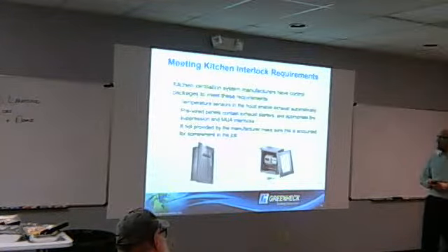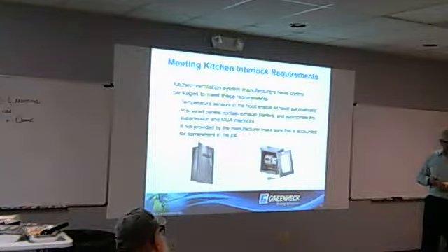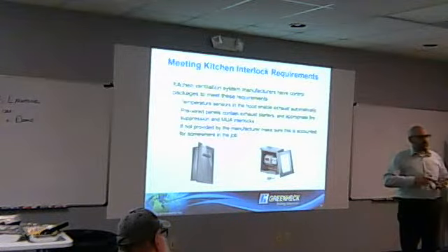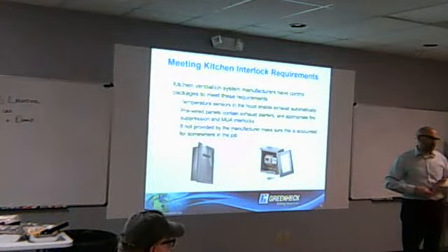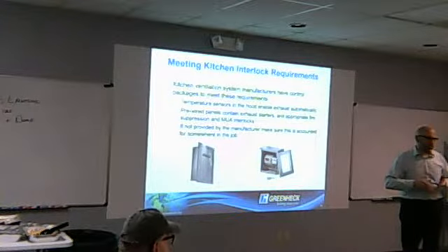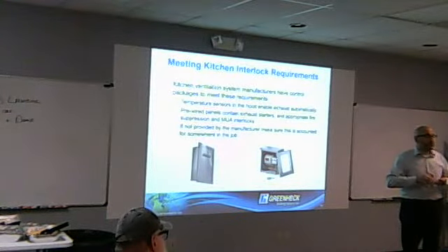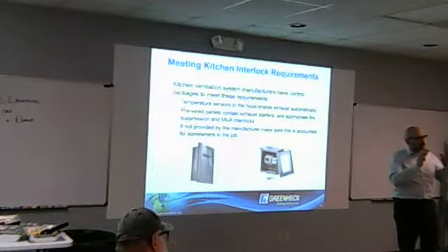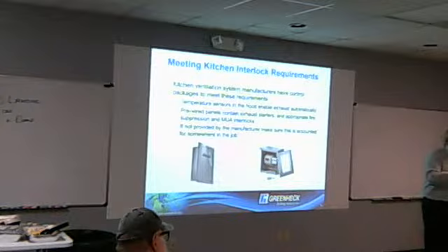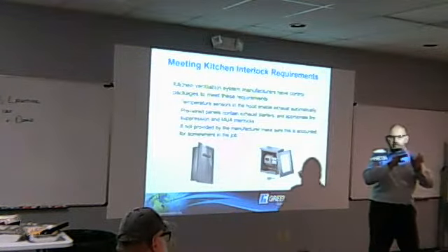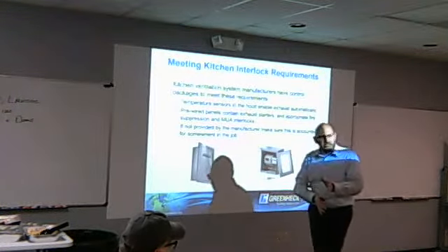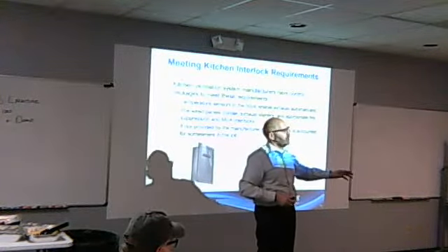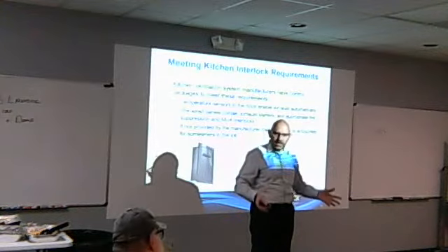Kitchen ventilation: we see a lot more requests for variable volume kitchens. You think of a kitchen with a big battery of cooking equipment, maybe a hospital, maybe a high-end restaurant, maybe a food court. Areas where you might have a big load in the morning, then a lull, then a big load at lunch, and a lull till dinner, and now you have another big load. Well, you don't want somebody turning on everything 100% all the time. They're not cooking all the time.